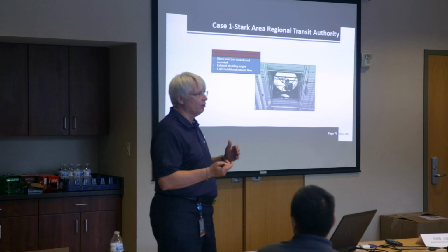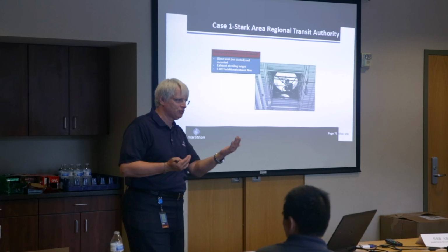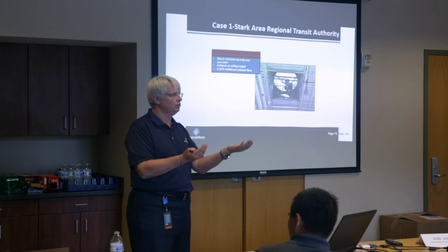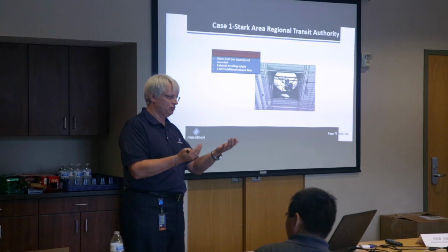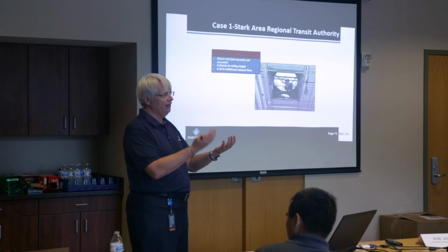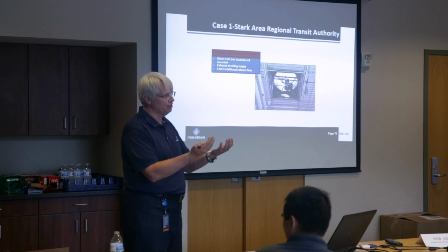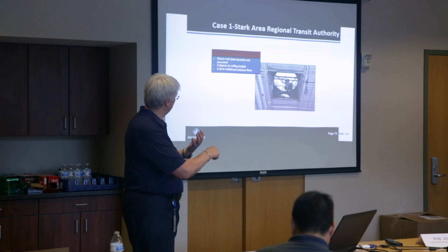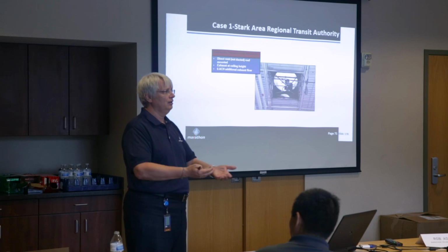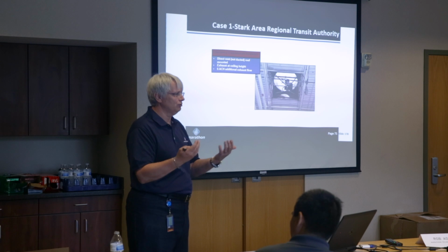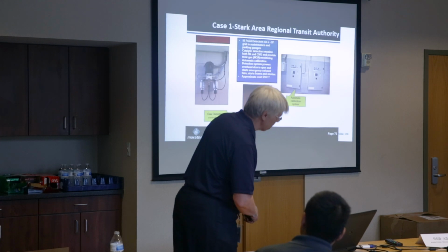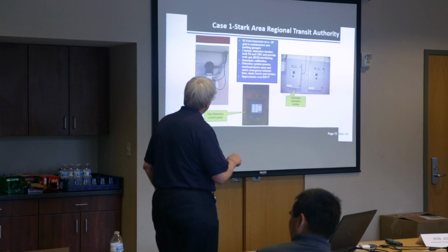So remember before we were talking about baseline exhaust versus emergency exhaust. Their baseline exhaust system is 4 air changes per hour. That derates the electrical requirement at the ceiling, so that's enough to take care of that. And then they've got supplemental emergency exhaust. Really, technically, they only needed 1 extra air change per hour. They've gone to 6. Again, more air equals more safety in the event of a release.